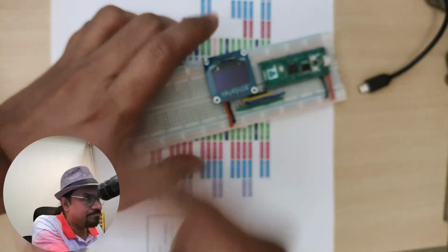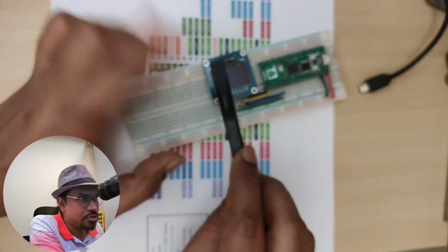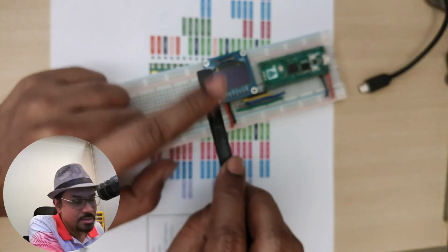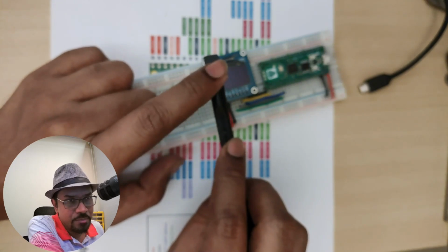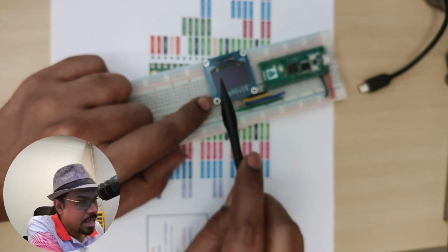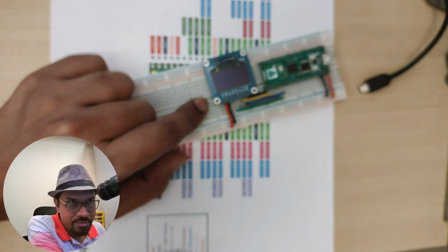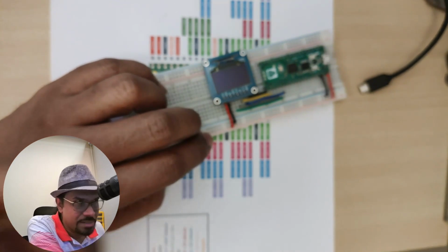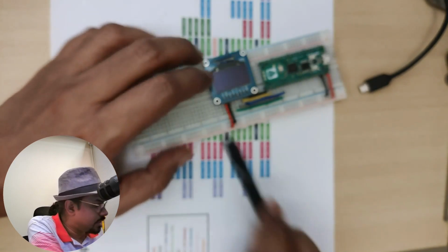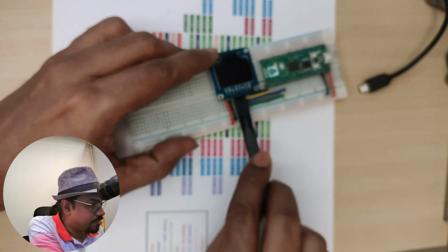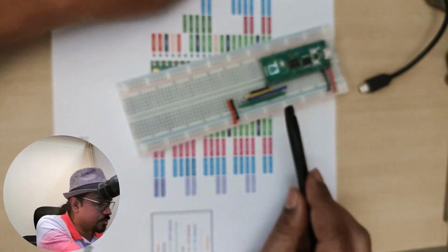By the way, it can be more snug on the motherboard. So if that's the case, you might want to use some tools like these. Make sure you use a plastic tool like this. If you use some kind of prying tool, make sure it's made of plastic. Don't use metal. They can damage the components. So be careful when you use a metal screwdriver. Use a plastic one, which is actually much safer to pry it. And yes, let's remove this display.